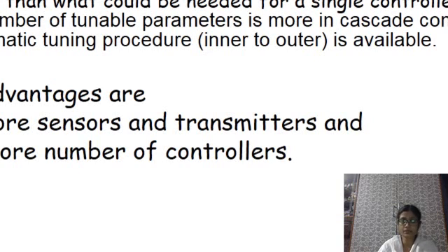Say for a temperature controller, for this example, the outer loop of the primary control system is the temperature control, and the inner loop is the high gain, faster response system, so that the disturbances that occur in the inner loop can be reduced before reflecting at the outer loop. That is the objective of using a cascade system.